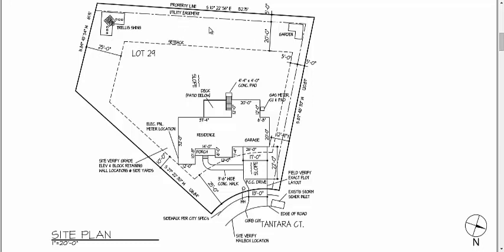Now this is a utility easement. What that tells me is there's probably electrical, maybe phone wire, cable TV, maybe even natural gas line that goes in that area. So let's say it's electrical, for example. Alliant Energy, if that were the utility company, they might need to come back and service that wire. Maybe there's a break in it or whatever. They need to have access to that area. So you have to reserve that space for them to come in and do that work.